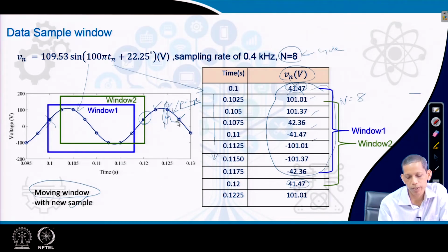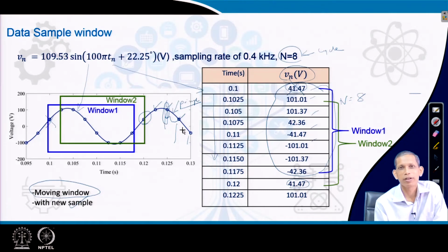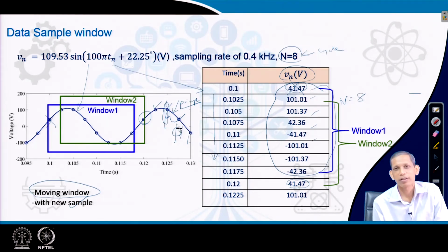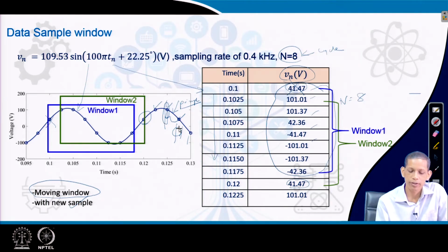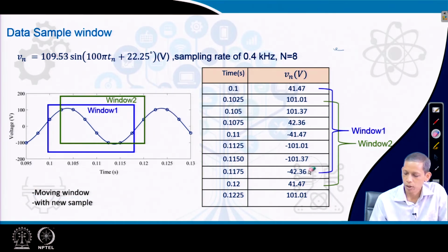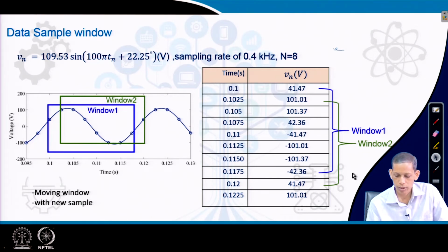Therefore, if the relay or algorithm uses higher and higher sampling, the interval available to the relay becomes smaller and smaller, but the relay has to take its decision within that smaller interval of time, and that becomes challenging. It has an associated cost, and that limits the design process. Based on all these perspectives, the relay has to take the corresponding decision for a successful operation of the protection scheme.